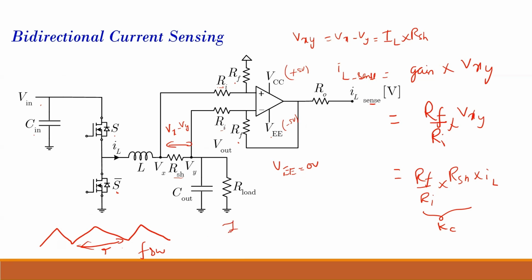So if you do a Fourier series, this current signal is made up of a DC term, the first harmonic at the switching frequency, then the third harmonic, fifth harmonic, etc. All these harmonics are there. So if I want to reconstruct this original signal, I must have the DC, third, fifth, seventh, ninth harmonic, all these harmonics' information.